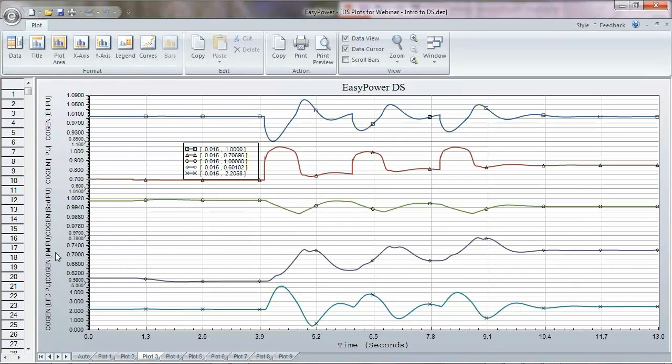Notice here on the mechanical power, first motor start, we step up to here. Second motor start, we step up to here. Third motor start, yes, we're at roughly, on the purple, 72%. If you look at the purple one, at 11.3 seconds, it's 0.719. So we're at about 72% of the capability of the machine. Okay, so that's a sequence.